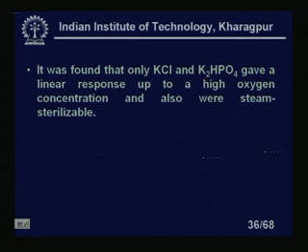It was found that only KCl and K2HPO4 gave a linear response up to high oxygen concentrations and also were steam sterilizable, right. So again, being steam sterilizable is a good property, and autoclaving is also a good property of the system. That is also something you always have to think about, because contamination is a great problem in all the reactions you will find, especially when you are using bioreactors. If you are using it in the field, that does not matter, because many reactions do not allow even a little contamination. You have to keep that in mind.